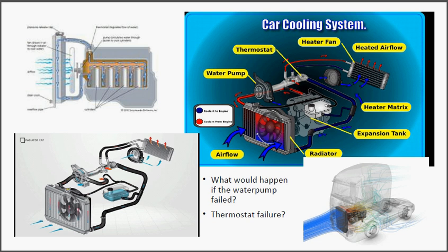The general fault tends to be that something goes wrong and the bimetallic spring doesn't work anymore. It's just permanently closed, and in that instance the temperature would just rise really, really high, and there's not much you can do about it. You would get the little warning light coming up, and you should really make sure you stop your car very quickly.